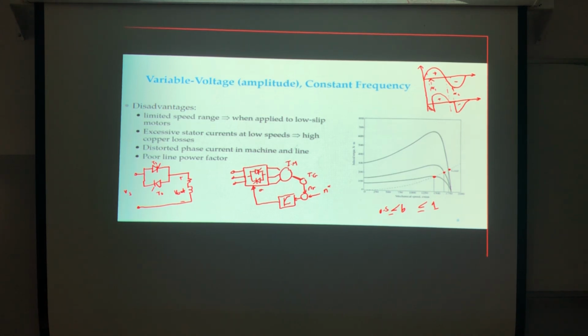So in general, we are not using the variable voltage, using the thyristor voltage control. Now, if I'm assuming discontinuous, this is the case if I'm assuming discontinuous. But is it not usually continuous in the case of induction? It depends, of course, but for the drive, for the machine, it will be continuous. So if this is continuous, this will be the scenario.